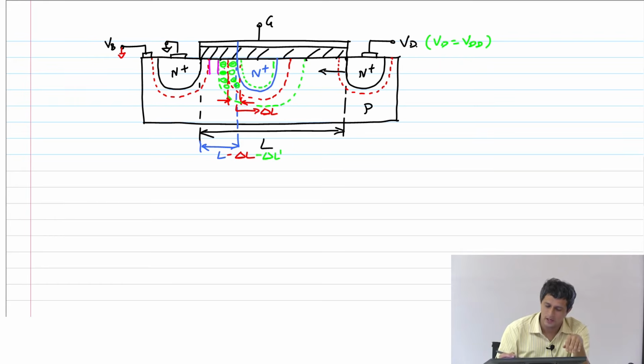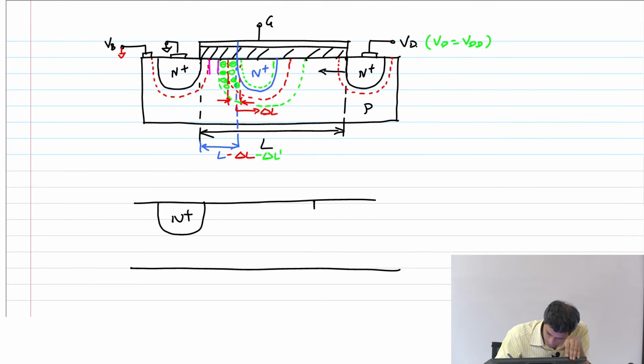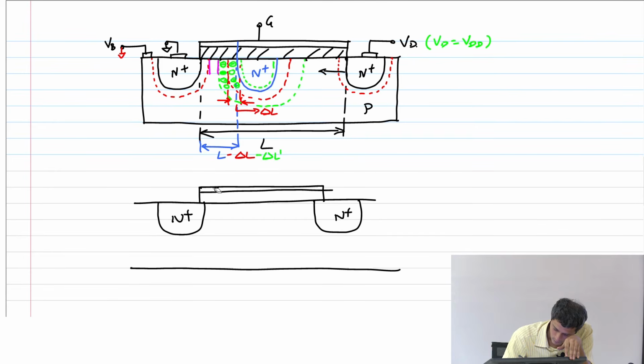Yeah, so basically what I am saying is that I'll maybe draw this a little bigger so that it's clearer, right? So I'm going to draw the short channel device now a little exaggerated. So this is my N plus, this is my N plus again, now I have my oxide, source is grounded, body also is grounded for my experiment here, gate potential and drain potential.